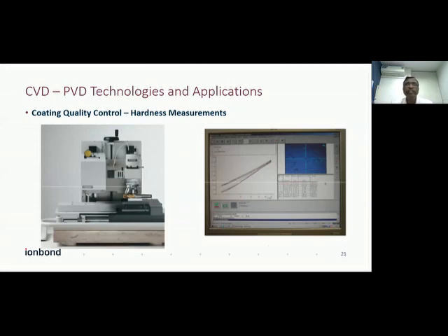So to measure the hardness within 3 to 4 microns, we can't use micro hardness, because in the micro hardness tester, the load applied is say 50 grams or 100 grams, 200 grams. If we apply that much load, then the indentation penetrates through the coating and touches the base substrate, so we get the compound hardness.